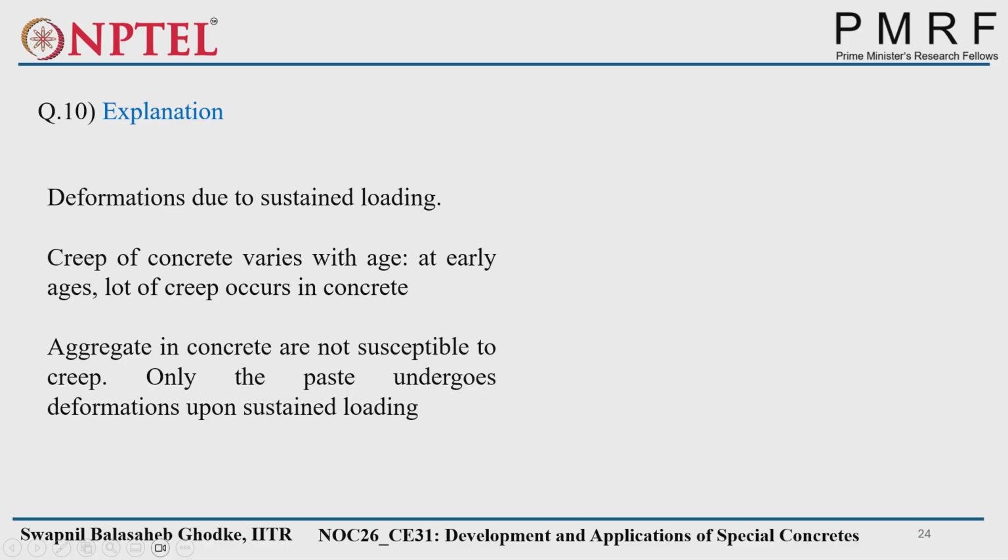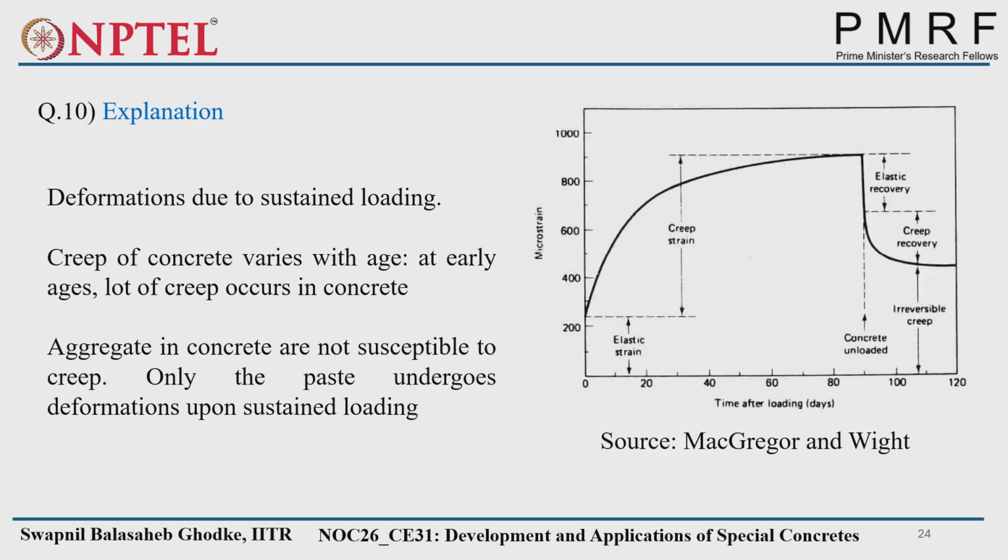So paste undergoes deformation upon sustained loading, and creep of concrete is a continuous process, varies with the age. At early ages it happens more, and at the latter ages it goes on decreasing also. With increasing age, the creep also goes on decreasing because of the decreasing deformation.